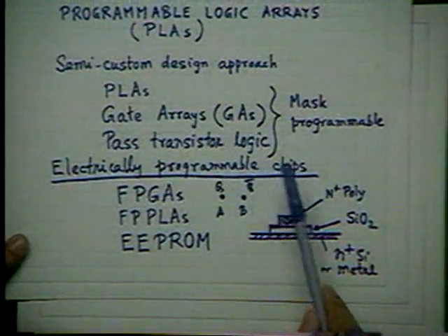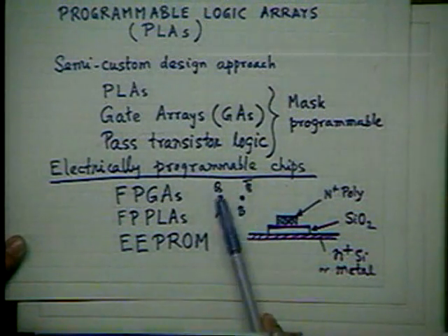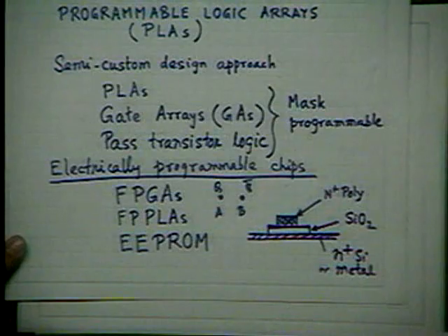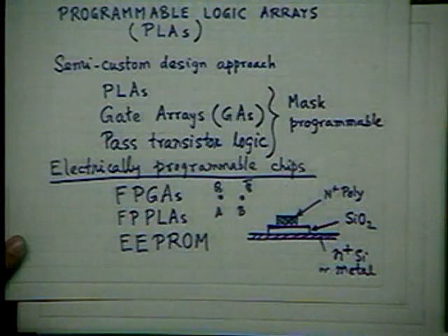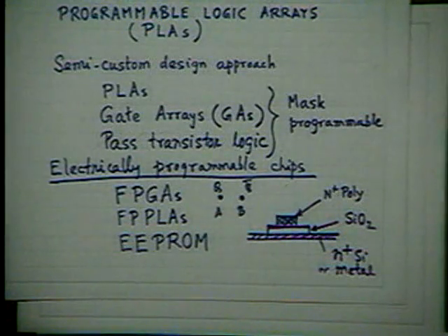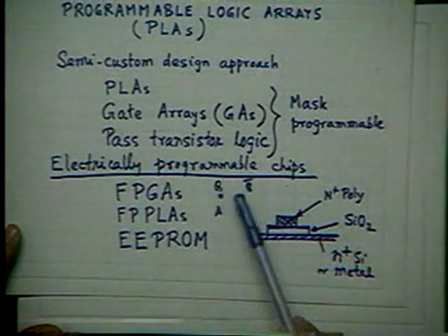When the switch is preset, then this Q is 0, meaning this voltage is 0. Voltage is 0 means practically a short circuit. Suppose I program the particular memory element which is connected between the two nodes. I program it to be 0, that means the output is preset to 0. Then points A and B will be short circuited. Node is established. And if I reset it, this is an open circuit.